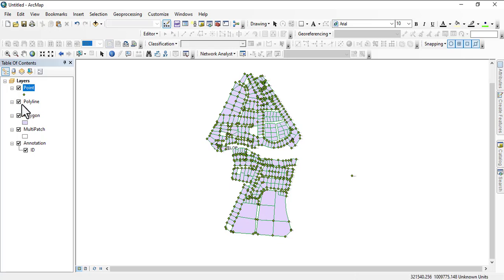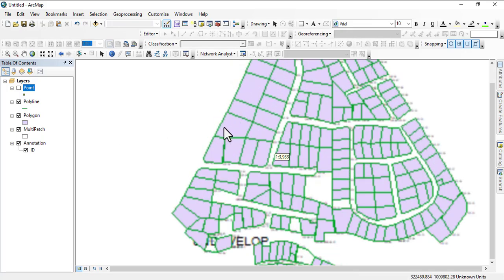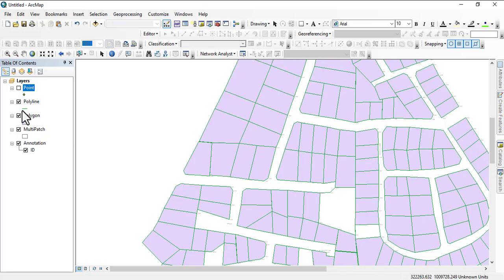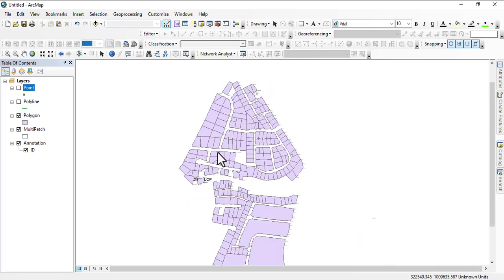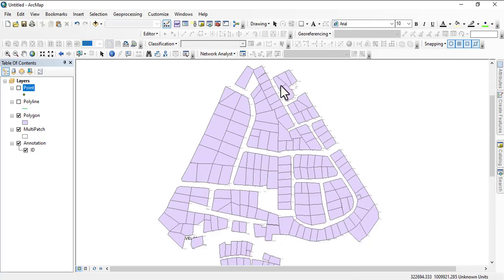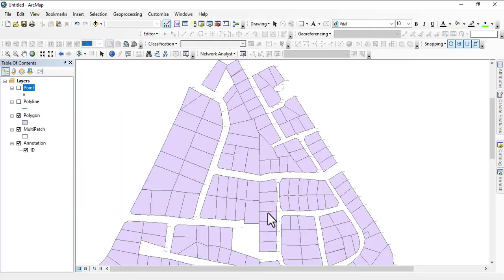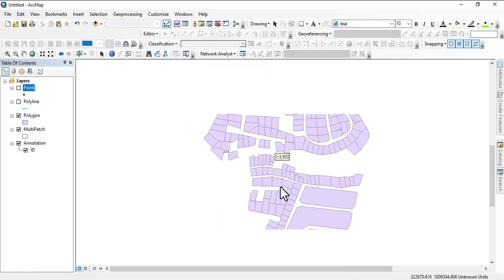All right, so the polyline now is the line which you've used in creating those things, because you need bearing and distance. So you use the polyline to bring out the bearing and distance, and then the polygon is another tool that you use to calculate the area of your work. You can see all these areas that are white indicate that they are actually road. The layout road has been made. These ones are some plots that are not even completed and all of that.